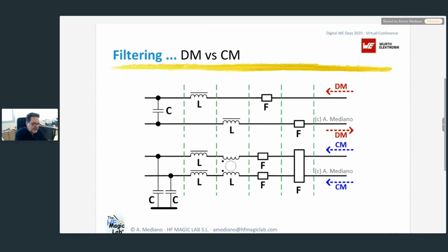The alternative to inductors usually is to introduce a ferrite. You can introduce one ferrite in each wire, or better, you can introduce one ferrite around the two wires at the same time. The difference is that usually with ferrite you will be focused in creating losses. And the second solution, the ferrite around the two wires, has the advantage that you will not saturate the ferrite, like is the possibility in the first solution. Remember, with two ferrites in the two wires, you will be additionally creating perhaps some kind of signal integrity problem, because two ferrites, one in each wire, is not invisible for the differential mode signals.